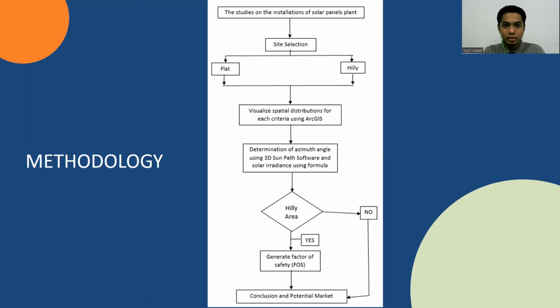I will present about our research project methodology. This is the study of the installation of solar panel plant, which is divided into two site selections, which are flat and hilly areas. After that, we will visualize the spatial distribution for each criterion using ArcGIS software. Then we will determine the azimuth angle using 3D SunPath software and get the solar irradiance using the formula. If it is a hilly area, we will generate a factor of safety using FOS. And then we will have a conclusion and also the potential of market.